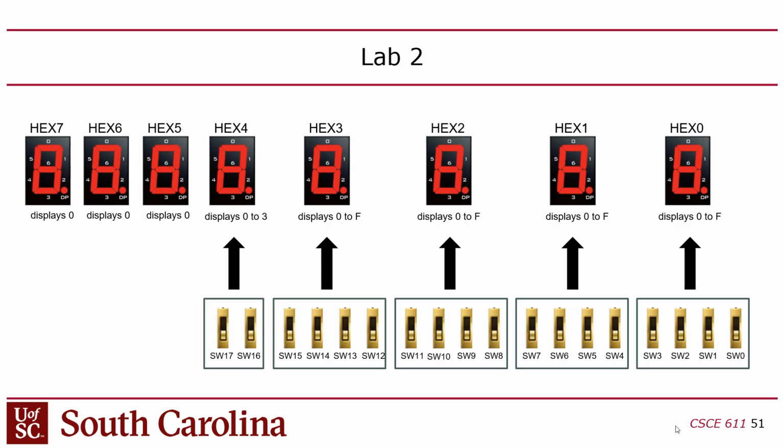7-segment displays are actually really 8-segment displays because they have a decimal point. But one of the problems with this board is they didn't wire the decimal point up, so there's no way to light that up. It's impossible. There's no PCB trace between the FPGA and the decimal point input on the 7-segment displays. That's pretty bad. But we can control the 7 segments, which means that there's basically 8 times 7, 56 bits coming out of the FPGA directly in here, which is nice because you guys might have noticed, if you see a typical 7-segment display like this and you film it with a camera, it looks like it's flickering on the camera because what's happening normally is that they want to save pins.